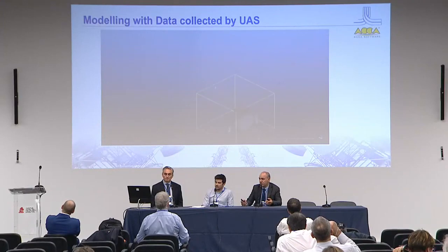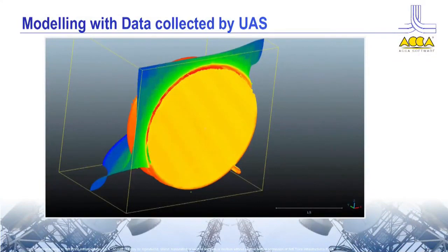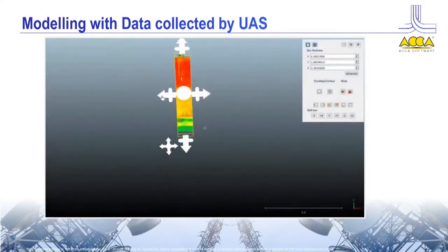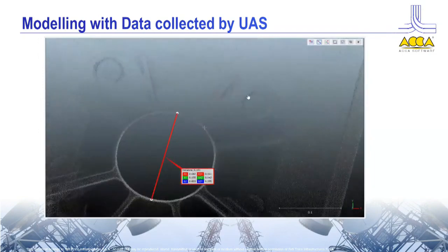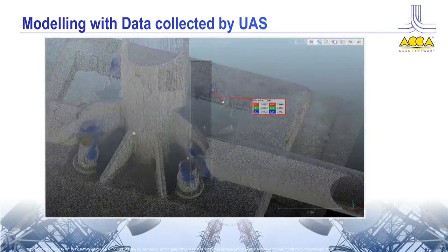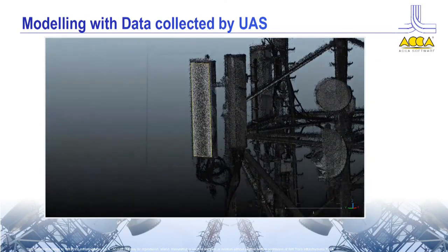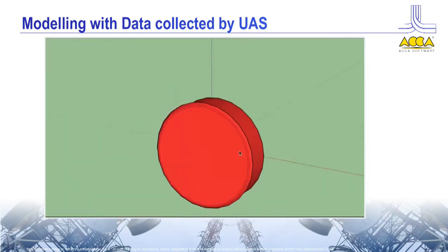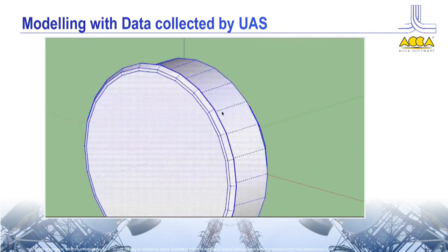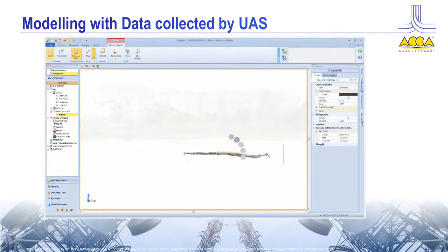We can briefly see some phases of this process on a parabolic antenna installed on a tower. We can reconstruct the mesh starting from the point cloud and then extract discrete profiles. Also, very precise measurements can be taken directly from the point cloud. For the modeling of this kind of profiles and deliverables, they have then been imported in parametric modeling software to obtain the definitive geometries.